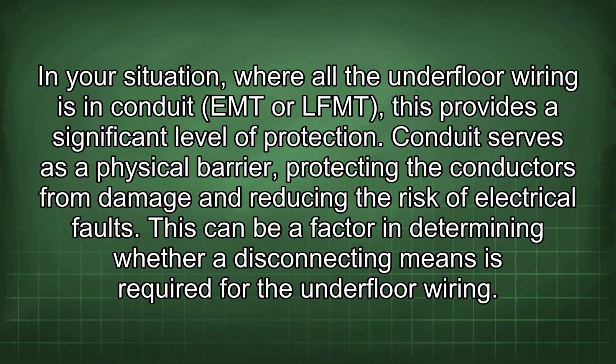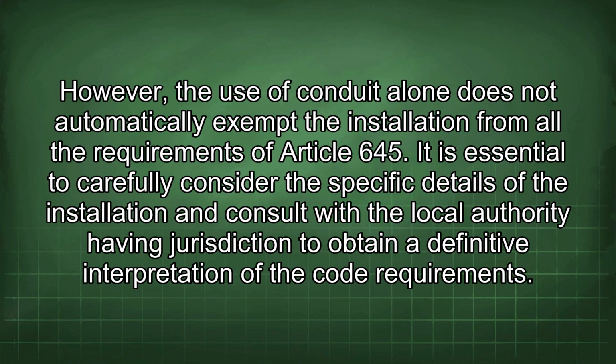In your situation, where all the underfloor wiring is in conduit, EMT or LFMT, this provides a significant level of protection. Conduit serves as a physical barrier, protecting the conductors from damage and reducing the risk of electrical faults. This can be a factor in determining whether a disconnecting means is required for the underfloor wiring. However, the use of conduit alone does not automatically exempt the installation from all the requirements of Article 645.